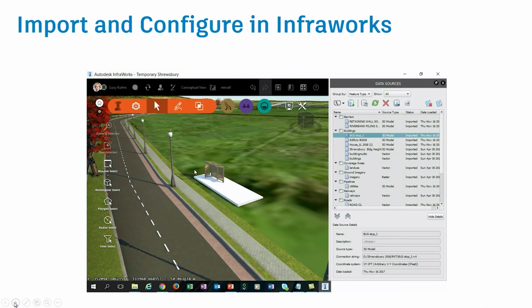This slide is already here about configuration, import configuration InfraWorks. As I suppose everybody here knows, you have the data objects like a Revit file, you import it there, and we establish a process to use 000 as our point of reference. So we don't need to play with coordinates to put our models in InfraWorks. We're going to show exactly that way, and I had a video that works.